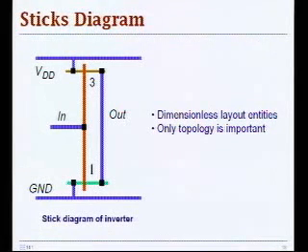And since these layout drawings can be really complicated, it is often a very good idea to simplify, at least in the conceptual phase, the way your circuit topology is going to look. And for that reason, people have developed this theory of sticks diagram. So this is basically a dimensionless layout drawing, and only topology is important. You just define the relative position of your objects relative to each other.